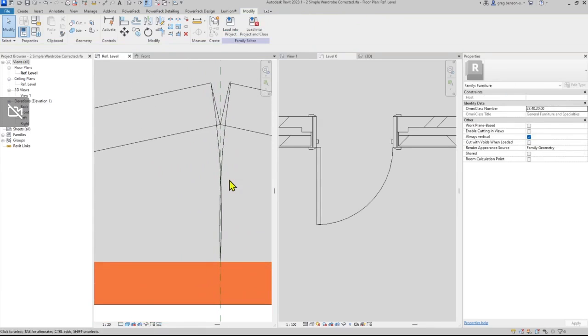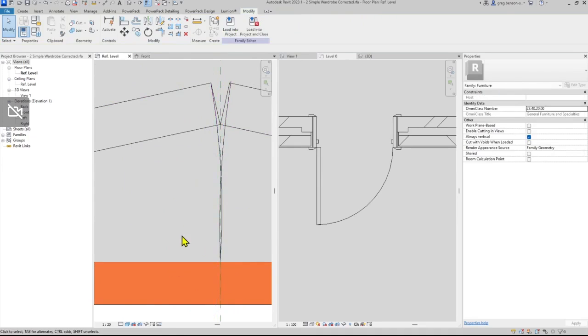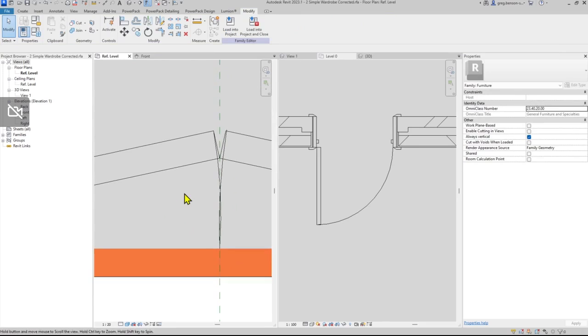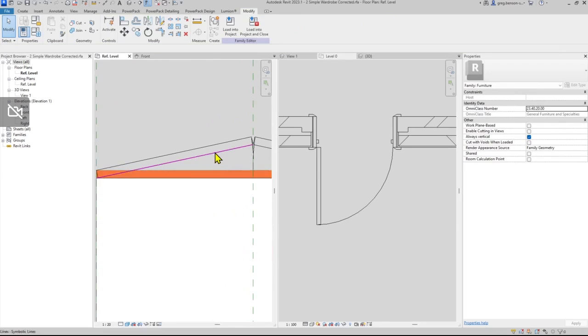Now when I do doors properly, I don't ever have my doors actually butted up like this. There's always a gap in between them because otherwise they don't physically open. And it causes us some problems, as you can see here. They're not great, but you get the idea. Now, let's change the level of detail that we get on the actual door itself. I'm going to hover, tab, see if I can pick up this whole chain.